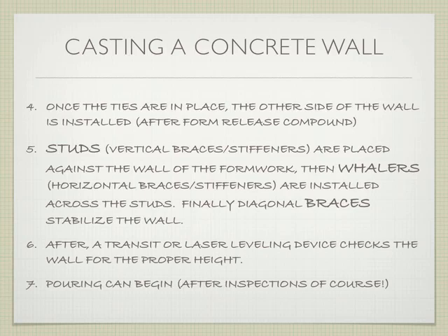Of a wall, it's usually dependent on the quality of the formwork. It's usually no more than 1 story, which causes you then to have to do a second lift. The problem is if you extend into, maybe you could get away with 1.5 stories if you had really good formwork. But it starts to get really risky, even at a full story, because if you don't have good formwork that's well sealed at the bottom, the liquid pressure from the concrete will cause the bottom of the formwork to want to bust out.